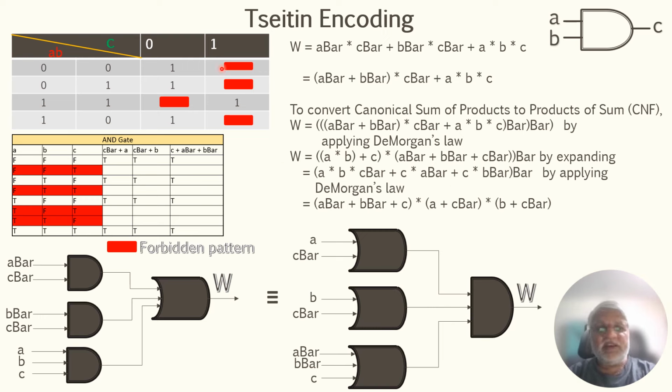So now if you read, each logic gate expression is represented in CNF form, where the satisfaction of each sub-expression enforces the proper operation of a single gate, in this case the AND gate. These are the sub-expressions of the AND gate. The satisfaction of the entire expression thus enforces that the entire gate is operating properly. So not only one sub-expression needs to be true, all the sub-expressions should be true. Then only we will say this W is operating, the gate is operating properly, because that is when we will say this is satisfiable.